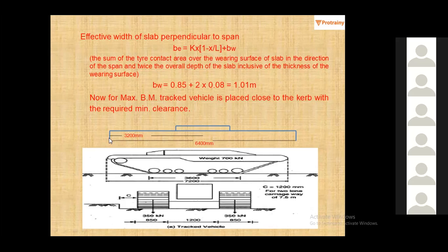That's it. Now you have to find out the maximum bending moment, which is going to be at the center, ठीक है ना? Because of the symmetry, we are just considering half of this span. Let's say it's a beam, we are just considering half of this beam. Now in order to find out maximum bending moment, क्या करेंगे?